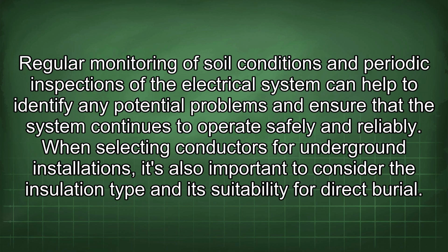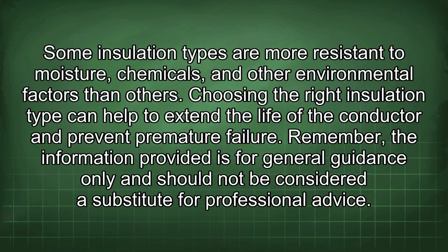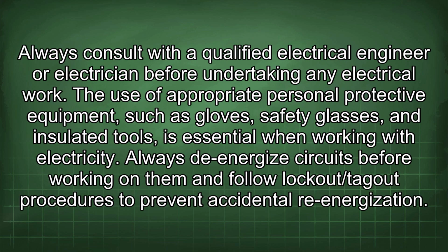When selecting conductors for underground installations, it's also important to consider the insulation type and its suitability for direct burial. Some insulation types are more resistant to moisture, chemicals, and other environmental factors than others. Choosing the right insulation type can help to extend the life of the conductor and prevent premature failure. Remember, the information provided is for general guidance only and should not be considered a substitute for professional advice. Always consult with a qualified electrical engineer or electrician before undertaking any electrical work.